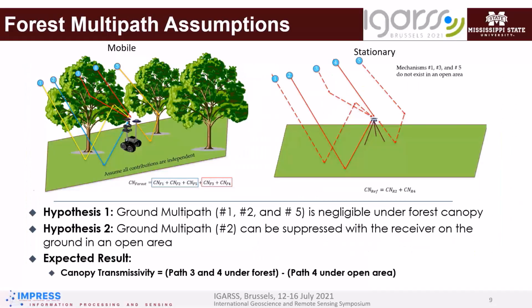The signals received under the forest canopy are expected to go through multipath within the vegetation and with the ground. As illustrated in the left side figure, the first-order scattering mechanism could be these 5 possible scenarios. Number 1, reflection from ground, followed by scattering from canopy towards the antenna. Number 2, reflection from ground. Number 3, scattering from canopy towards the antenna. Number 4, attenuated direct signal. Number 5, scattering from canopy, followed by reflection from ground. Among these paths, numbers 1, 2 and 5 involve ground reflection, which are undesirable since they can distort the difference methodology if they are substantial.